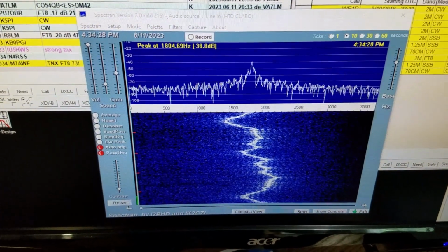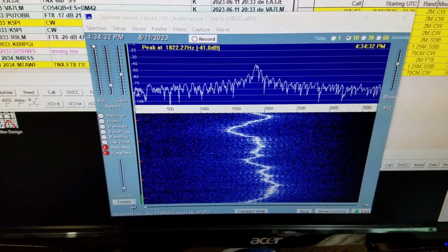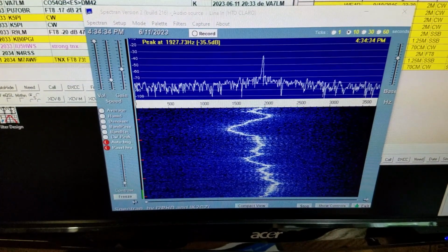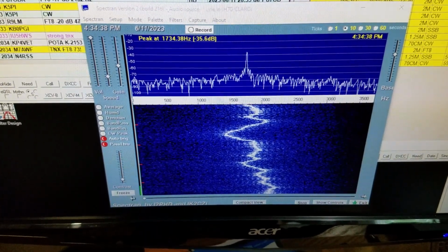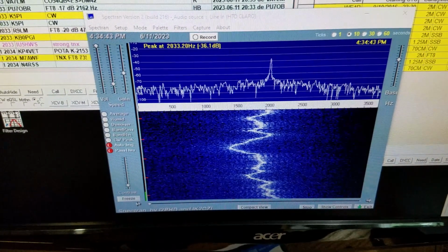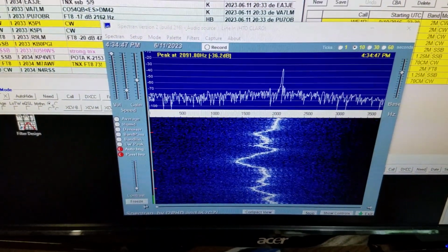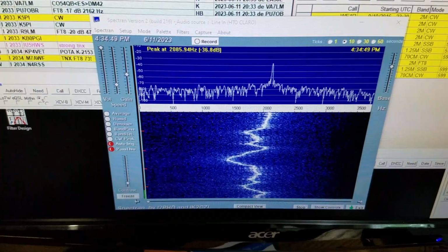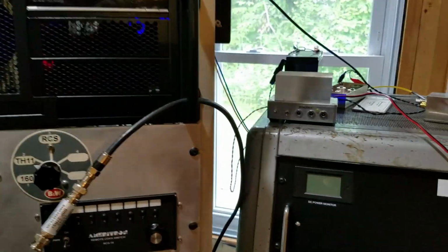But remember that at 106.5 megahertz at the crystal oscillator frequency, this is only about 5 or 6 hertz of drift, which wouldn't be bad for a crystal oscillator at VHF. But it's just multiplied up so many times, and the drift gets multiplied as you go up in frequency, so it's not very stable. And this is all coming from the oscillator in the transverter here.